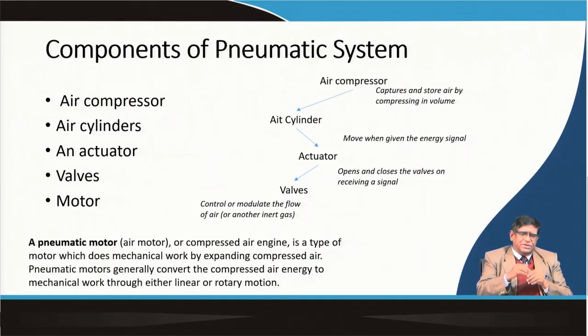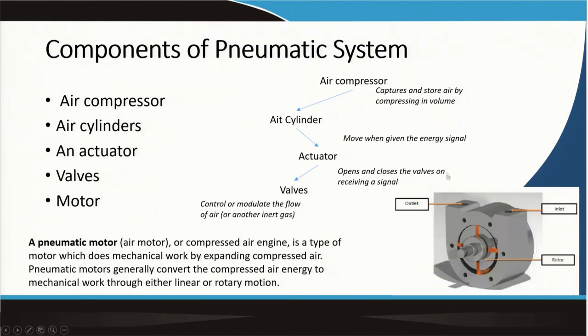And of course, there will be some air motor, where the compressed air will be going and generating the rotary motion. As I said, in a rotary blast hole drill, the air motor is used for making the drill rod rotate. When you will be studying this pneumatic drill, you will be using these things. In an air motor, you can see that compressed air goes in through an inlet, there is the rotor part, and then the air goes out through the outlet.